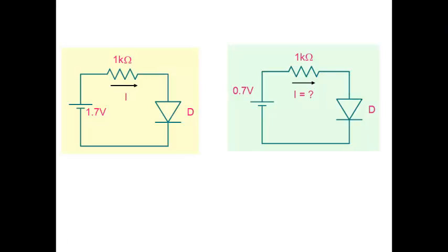Now you start using this particular model here with a 0.7 volt source and you put 0.7 volt here, obviously you're going to get the wrong answer. You're using it at the wrong place. And so that's what I've been cautioning you, that yes, we learn a model and we forget where to use that particular model. We start deploying it everywhere. And in this case, if we start deploying it, we get a wrong answer. We can't assume it to be a 0.7 here.